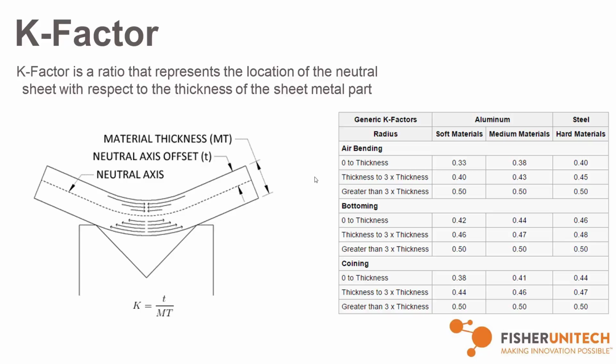I've talked to a lot of support people about this one, and a lot of times they'll start tinkering with that K factor number and can't get to a good solidified spot. Maybe their flat or blank is coming off wrong. There are tables out there to help get you at least closer, and that's what this thing over here is. Depending on the process or metal you're using, there are good default places to start. Otherwise, SOLIDWORKS is going to give you a 0.5 K factor by default.